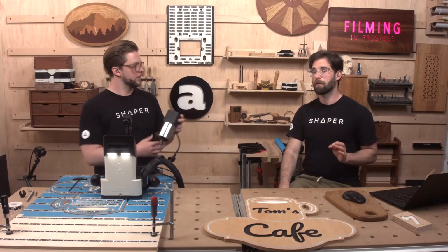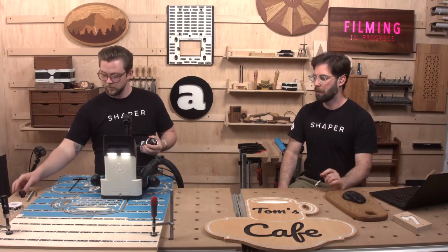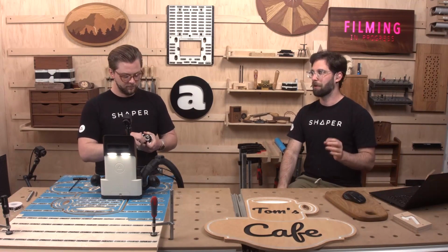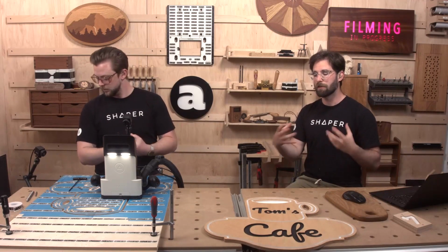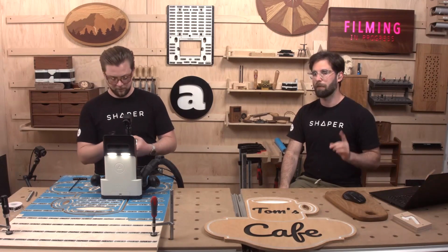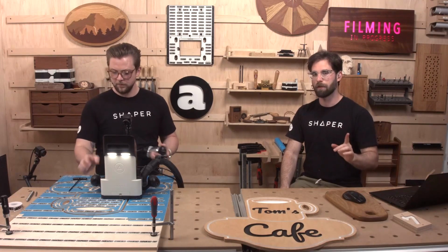The router bit that we use for that is an 1/8 inch, usually by 1/4 inch O-flute router bit. Stubby, strong. Yeah, all of those parts of that are important. O-flute, because it clears those brass chips really well. O-flute is a very specific type of single flute, one flute geometry for a router bit. So O-flute's important.